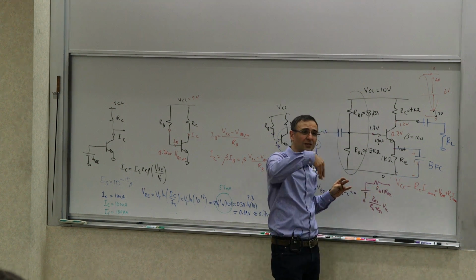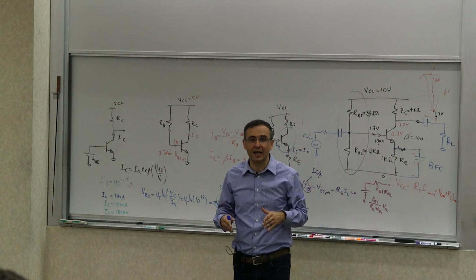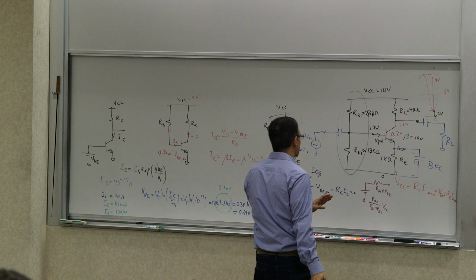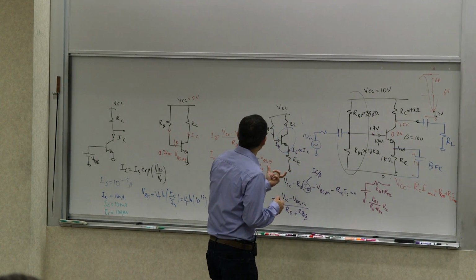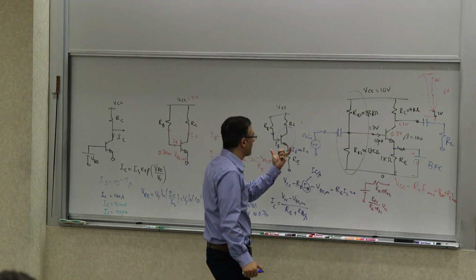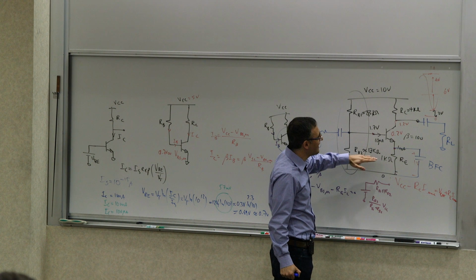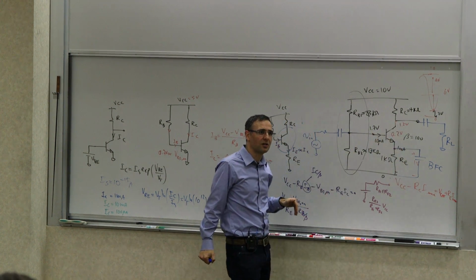And we'll take multiple steps over time. As we go later on, we'll see that there are much more sophisticated ways of generating these currents and voltages to make the gain independent of temperature and voltages and things of that sort. That will evolve out of this. But this is a very basic, classic, low frequency, or discrete amplifier. Now, in integrated circuits, you don't see these kind of bypass capacitors as much.